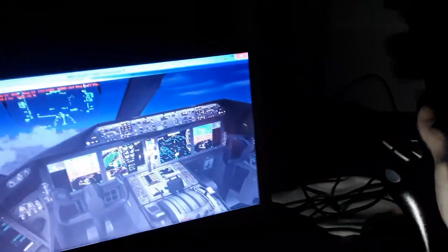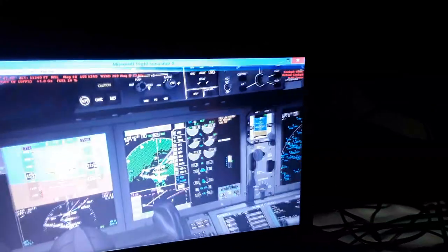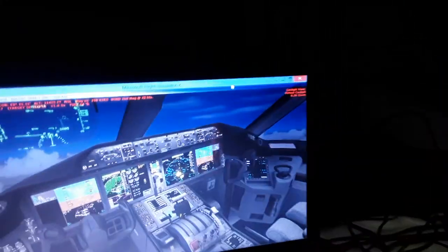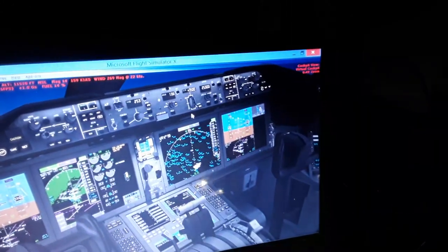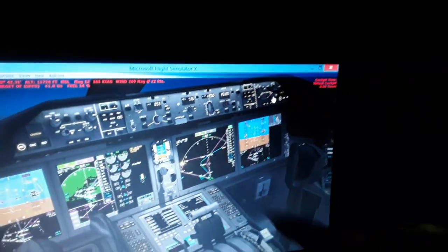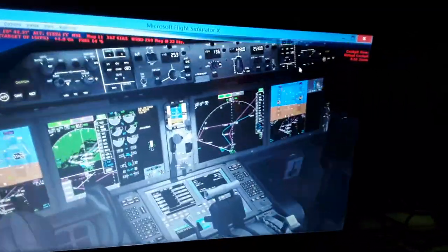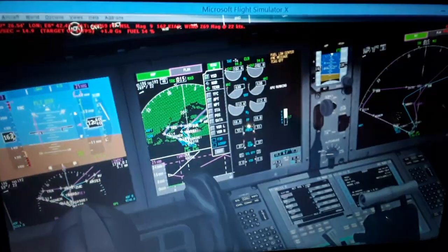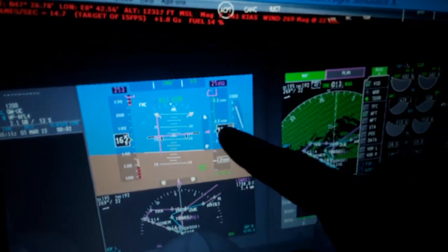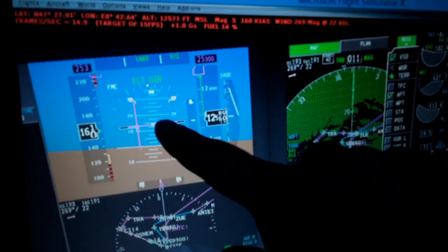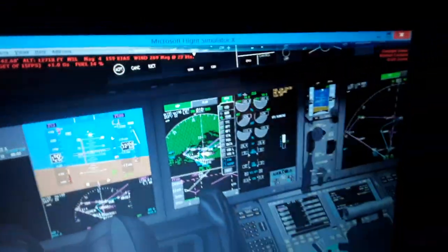Pitch down a little bit more maybe. Climbing 11,000. Also here the indications. You will see the flight plan with the magenta or purple line over here. We need to fly through these waypoints, as I told you. You can see the terrain with green. Also the airspeed here, the stall speed, the altitude we are, rate of climb, pitch attitude, like 13 degrees right now.